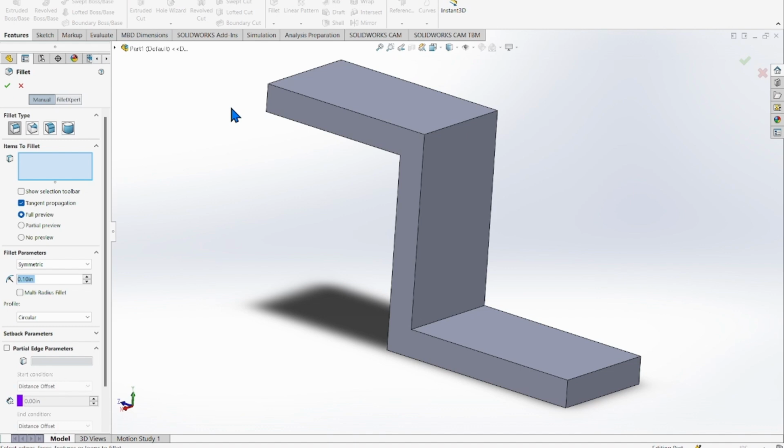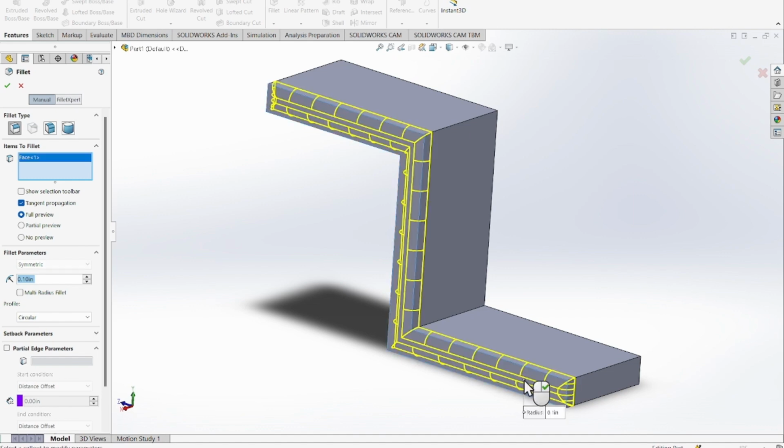Okay, next one, our indication will be this guy right here. We're gonna select this little line right here. Do not select the face. You notice that it turned orange on the face. I'm gonna move out of the way. You notice that the coloration, it'll select the whole entire face. If I accidentally click face, this will indicate that your item selected will be on face.